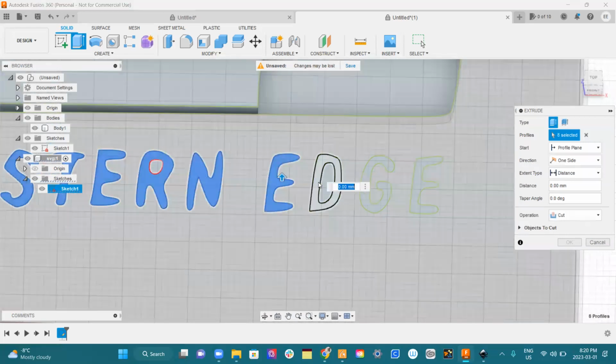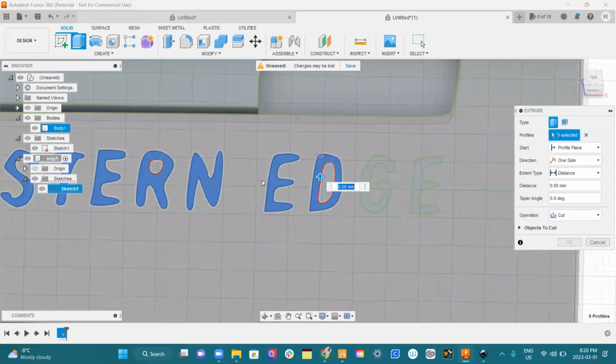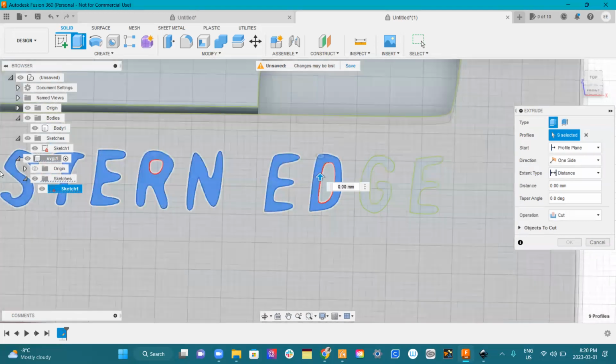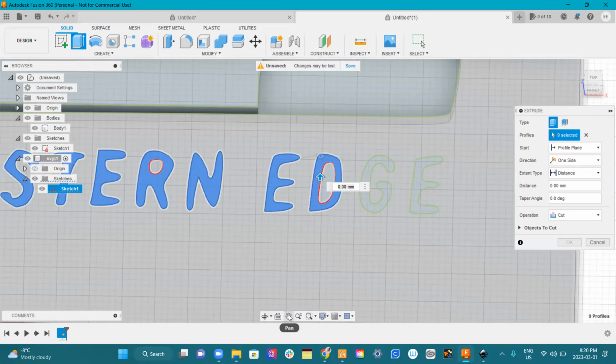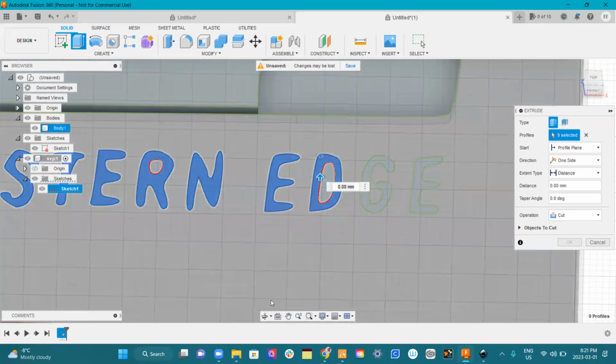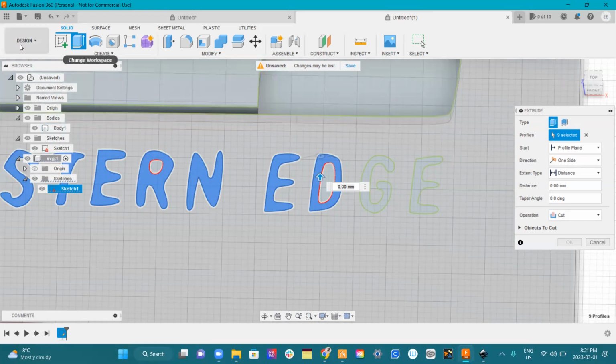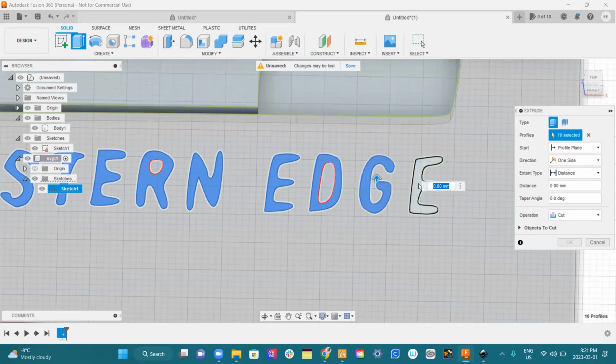Are you holding shift while you're clicking on it? Yeah, I'm hitting shift. The controls here, if I scroll, it zooms in and out. If I click the scroll wheel and drag around, it will pan around. And if I hit shift and then click this thing and drag it around, it will orbit. There's a lot of little things. There's also icons, so there's orbit, pan, zoom. Icons you can click if you don't know the hotkey versions of it. And there's a lot of tutorials, so it's worth doing that if you're getting into it.